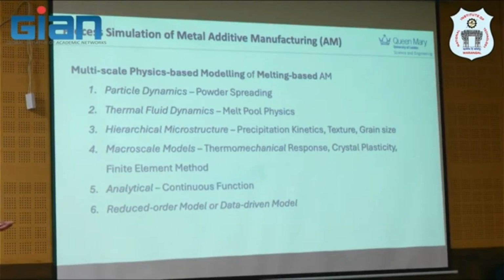So how this emerges as printed is something we probably need to understand a little bit, because if we do differently in terms of heat treatment, you may precipitate out some particles wrongly or not as you want. So again, this contributes also to grain size or texture. Texture control is also another matter, so we will talk more later. And another meaning of modeling, or another scale, I would say, we talk into the scale.